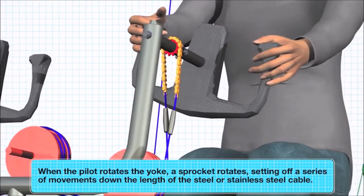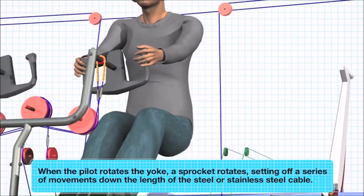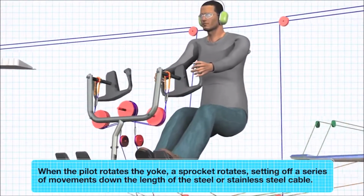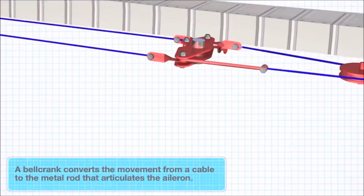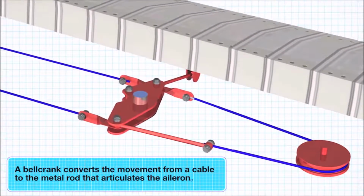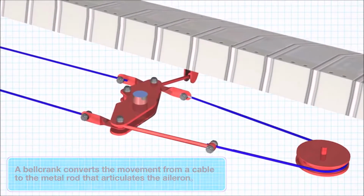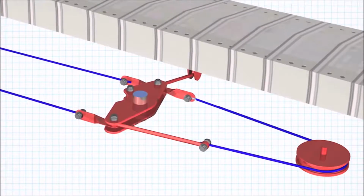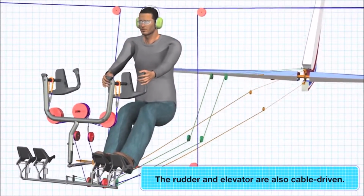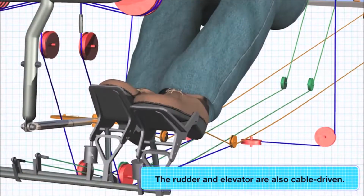So when the pilot rotates the yoke, a sprocket rotates, setting off a series of movements down the length of the steel or stainless steel cable. A bell trunk converts the movement from a cable to the metal rod that articulates the aileron. The rudder and elevator are also cable driven. So here, they are operated by the pedals.